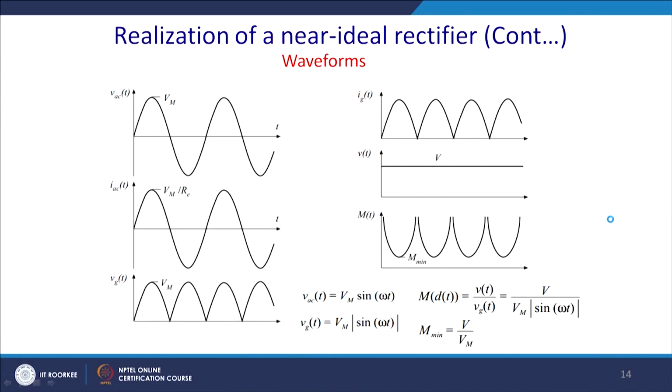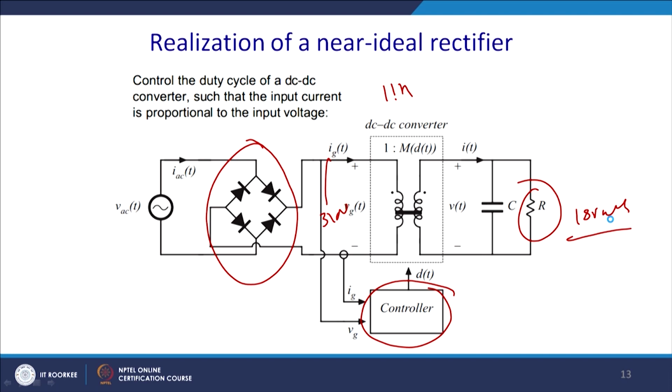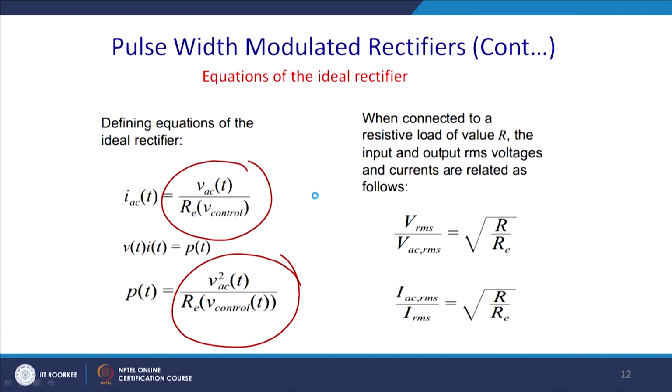So, we have Vm that is varying, and please note the different voltages here, since it does not have any capacitor. So, this point voltage will change according to the input voltage. So, you have just double frequency ripples, that Vg will be a 100 Hz ripple DC, not a constant DC. But if you do that, then you distort the power factor. For this we do not do that.